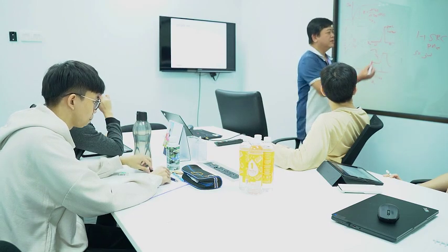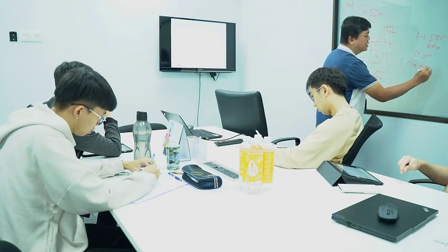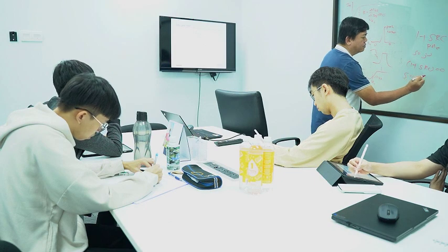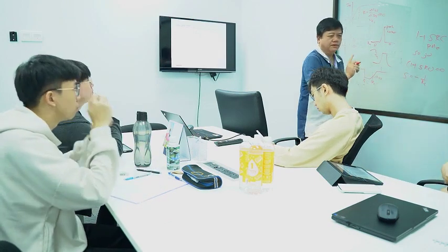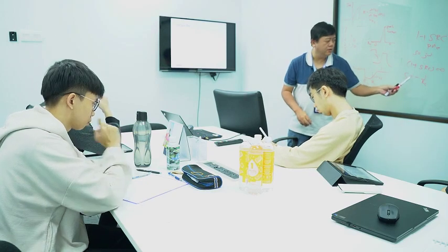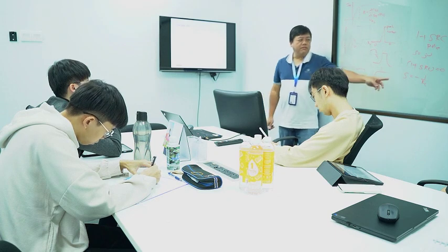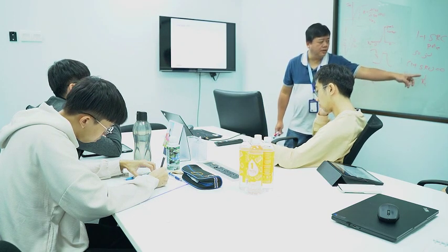So that's why normally we set 1 plus SRC equal to 0. From there you can find out what your S is. S equals negative 1 over RC. When you have negative, that means stable. So this defines your S here, and this defines your cutoff frequency. You want to define the cutoff frequency, that's why we have this.